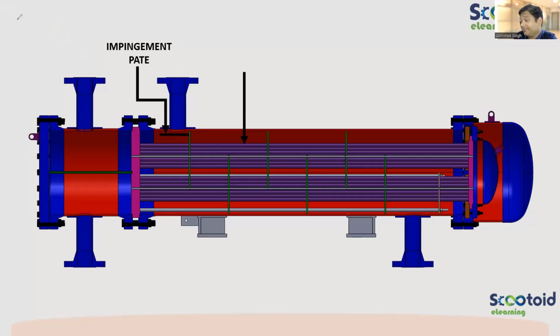Vamo, when it will be there and when it will not be there, for that also the guideline is there in TEMA. When we need to provide this impingement plate and when we don't need to. You can also say by engineering judgment, just by logic, when do you think it will be required? When do you think it will not be required? Tell me, just by logic, what we already saw: because of the flow of the fluid coming directly on the tubes, flow rate, Weber, absolutely right.